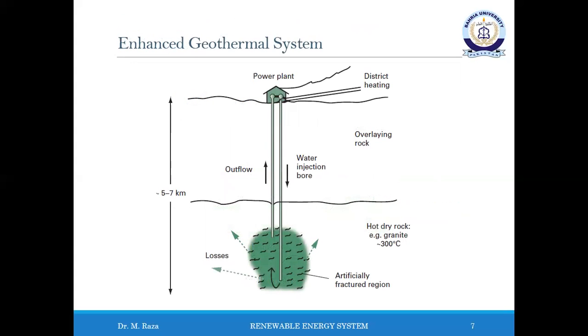The most important rock properties within the aquifer include grain size, shape, and porosity. How these interact with each other also determines site potential, along with any fractures or weaknesses in the layer of the rock. The fluid pressure gradients and volume of water flowing in the rock are also key considerations, and systems are measured in hydraulic conductivities. Fluid pressure can reach up to 10 megapascals.